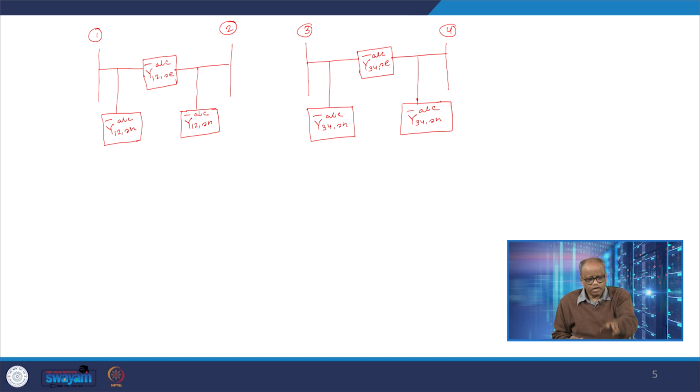So this is the network, and between bus 2 and 3 there was a transformer. You see, I will simply omit that. So now I have another network in which we have essentially retained everything of the original network, but we have simply removed the transformer connections. Now, because this network comprising all these 4 buses does not involve any transformer, it will follow the earlier rules.